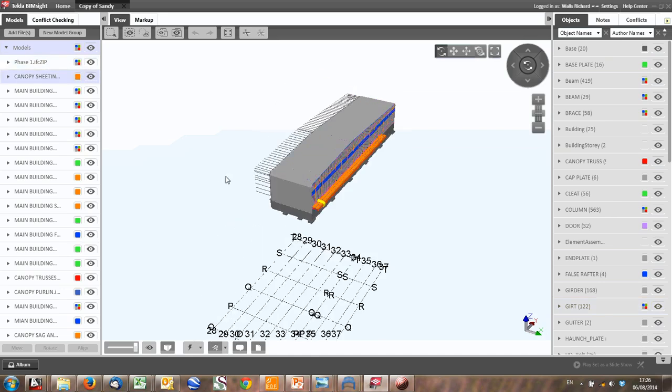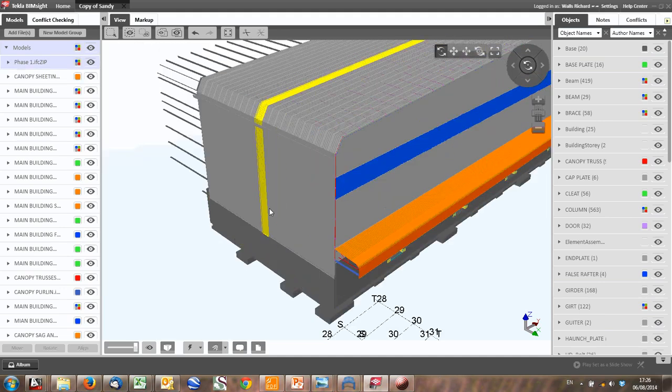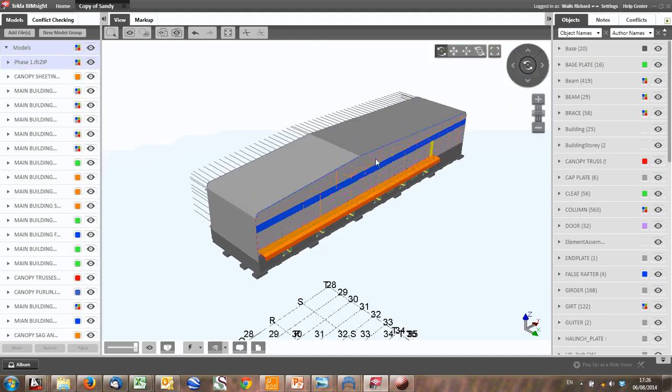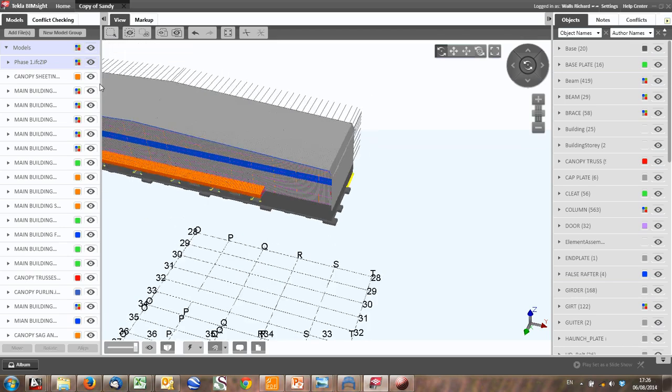Here is our model. And what's quite nice is you can actually see there's our sheeting. So you can imagine wind coming on, hitting the sheeting from this side, or wind coming on, hitting the sheeting. And just be careful on these big warehouses. Have a look at the wind load code. You also have to consider friction forces on top. Friction forces are generated as the wind travels across. You may need to add those as horizontal loads.